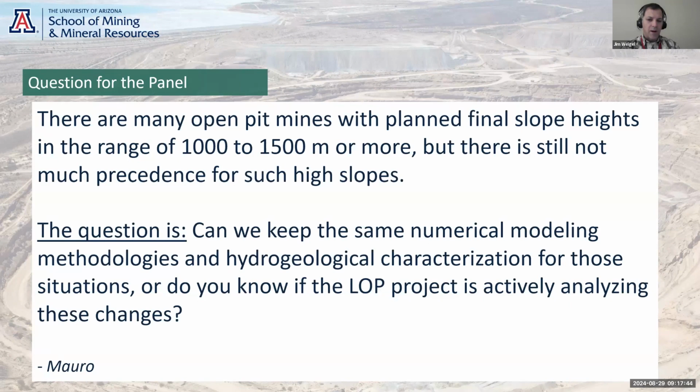So oftentimes what I find is I'd much rather stick in 3 different strings of instruments than, say, one pumping well and do an aquifer test on that one pumping well. Those 3 different sets of instruments or strings of instruments can be way more insightful than one pumping well, where you might not be able to see the effects of that pumping well more than 150 or 200 feet away.